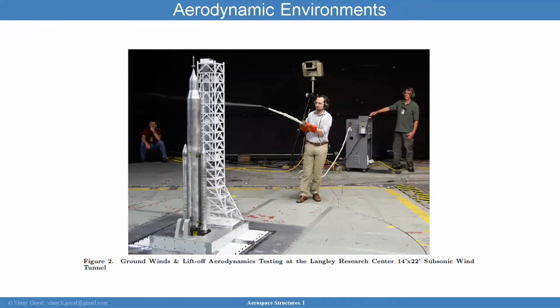It's going to give you static pressure measurements also, which are distributed spatially on the vehicle and can help you then compare to CFD. And it's going to help you with the determination of the aerodynamic loading on the external components of that vehicle. So very important testing that provides a significant amount of value on this kind of analysis.